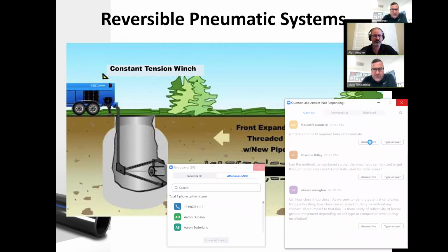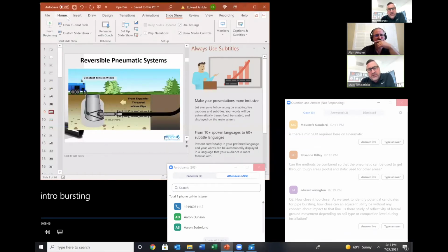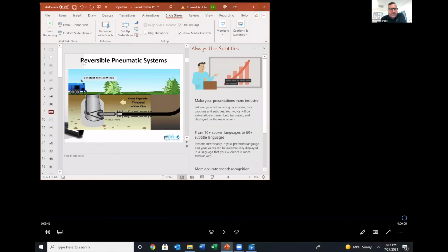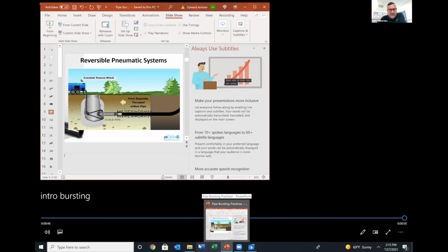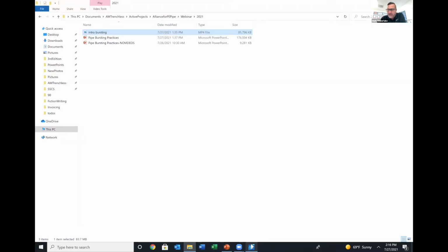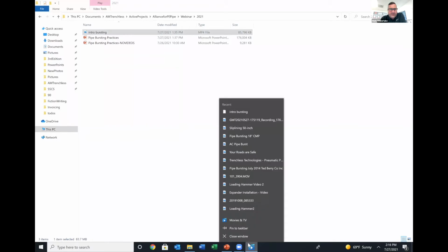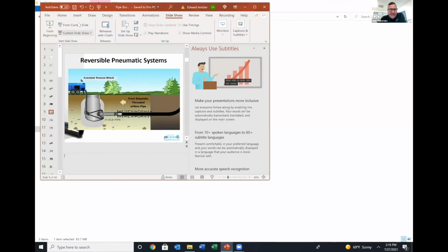If you look at this photo, that again in small diameters, 6, 8, 10, typically as large as 12-inch pipe, we can actually set the winch up into a receiving manhole, and then when we land that head in the manhole, we simply cut the head off and back the tool out. And in some applications, that will eliminate that downstream or receiving pit.